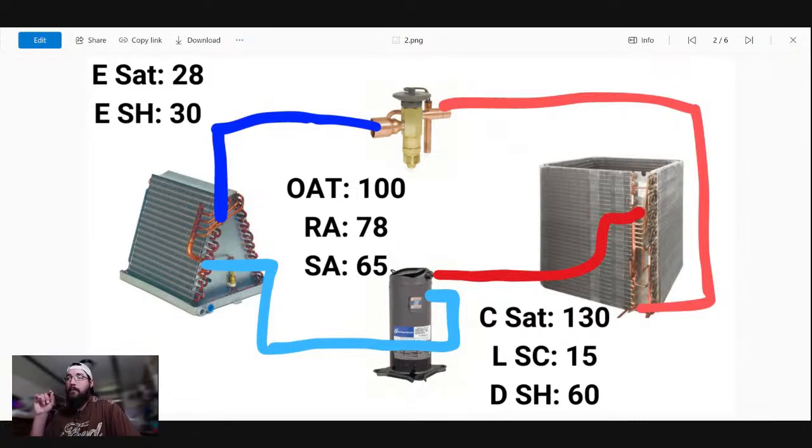All right. So yes, if we could start pushing in on the TXV itself. Ultimately, the TXV is a pretty strong culprit here. We're backing up on our condenser side. We're running low on the evaporator side. We're not keeping up with the heat in the space.